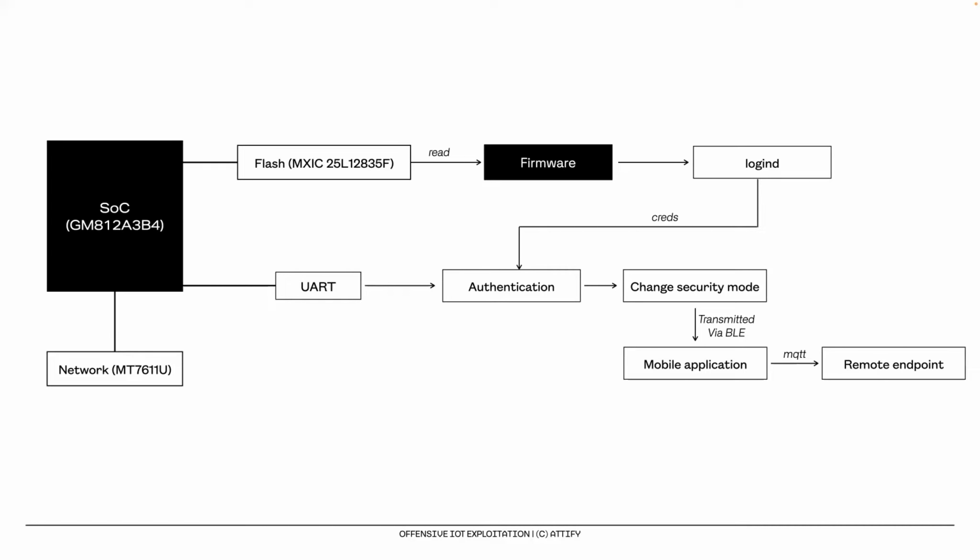Now, one way of obtaining the authentication credential or obtaining any kind of data that is stored on the device is using this element of flash chip. So flash chip is what holds data. And because we know the pinout, we can interact with the flash chip and read all the data from it, which is what will be the firmware. Oftentimes, it could also be other kinds of data storage. But if we are able to read from the flash chip, here we are getting the firmware.